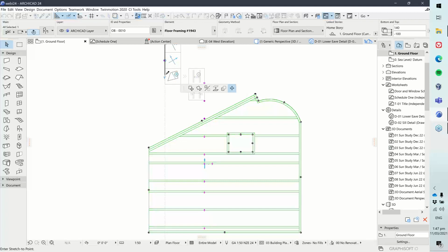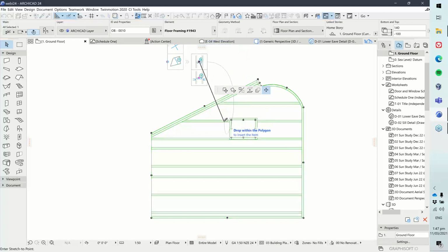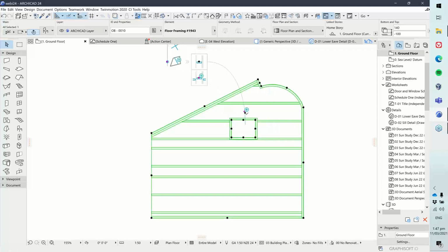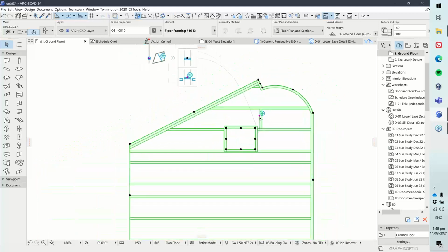And then the last option here is the internal layout, which is probably the part that you're looking at this floor frame and thinking that it's completely missing, is this part here. So what we're going to do is we're going to add some by clicking this purple node here. And you can see, started another one. As I dropped this node onto here, it's added a vertical part into these horizontal frames.